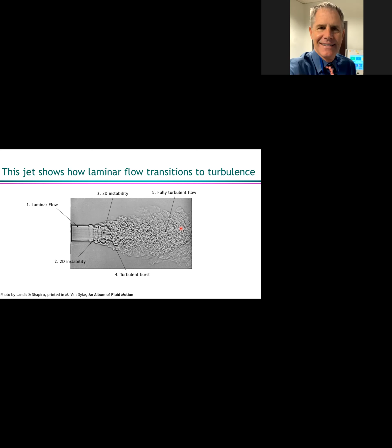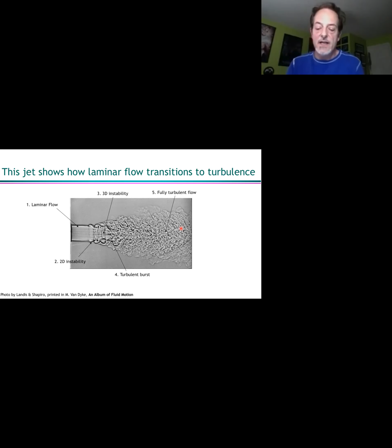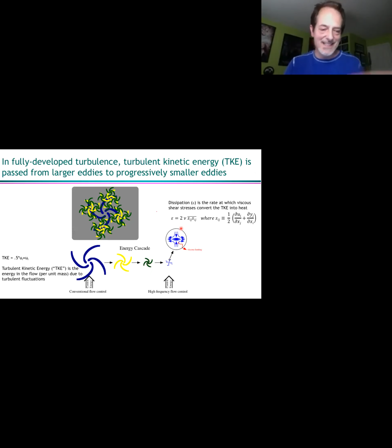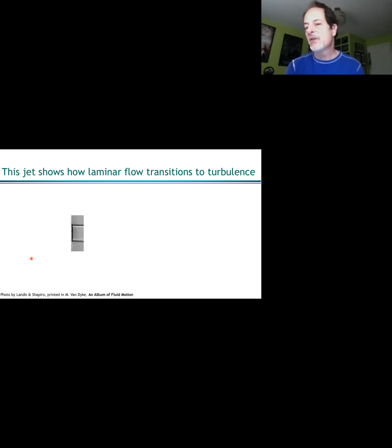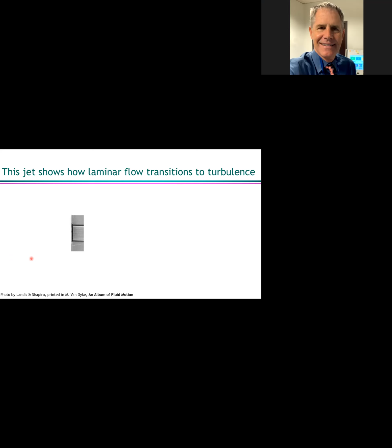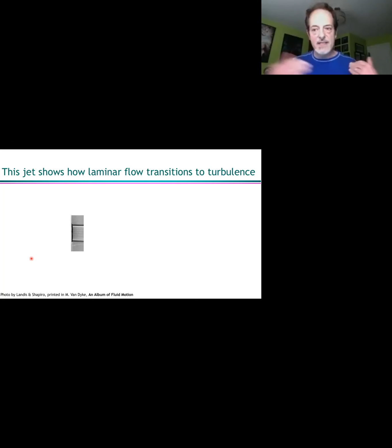Can you define laminar, John? Laminar flow, I talked about, if I go back one slide, I don't want to go back too many slides because otherwise I'll never get done. So I talked about turbulent kinetic energy, where you have velocity fluctuations. And the turbulent kinetic energy is basically the sum square of all the components of that. To me, a laminar flow is just one where those velocity fluctuations are very, very low. Typically if we're making a wind tunnel and we want nice laminar flow, then those velocity fluctuations will be on the order of 0.5% of the mean flow or something like that.